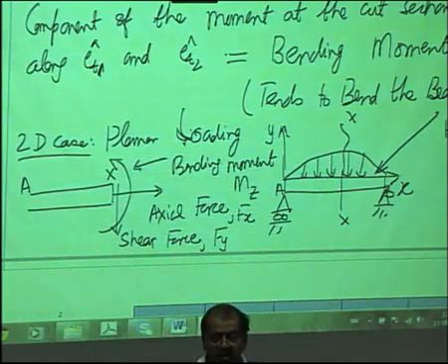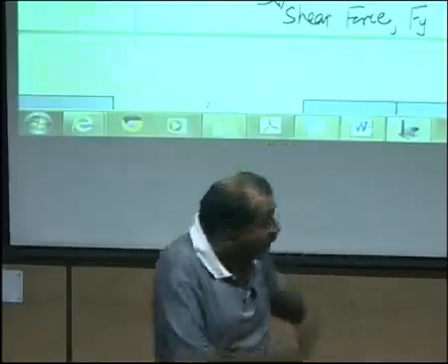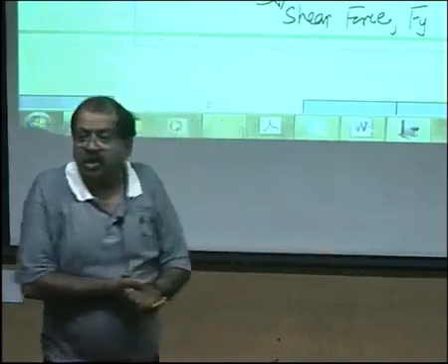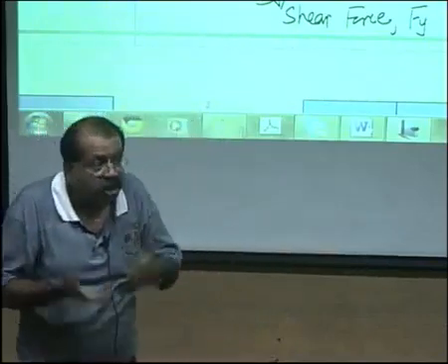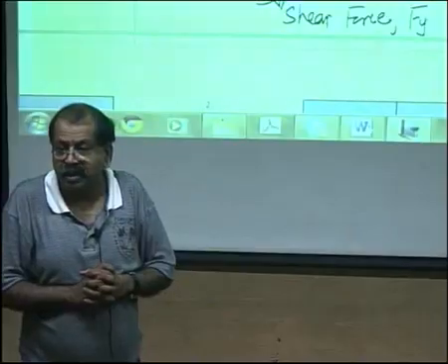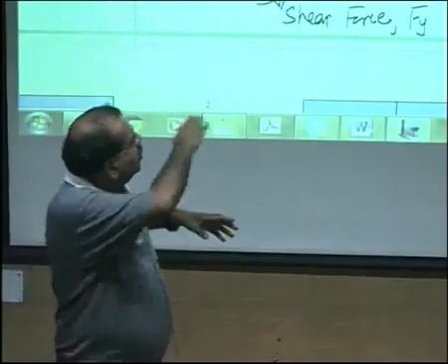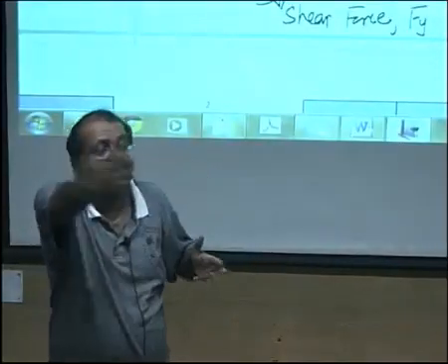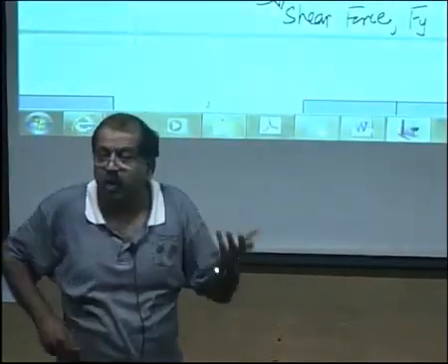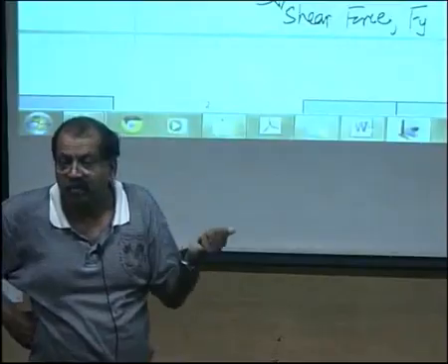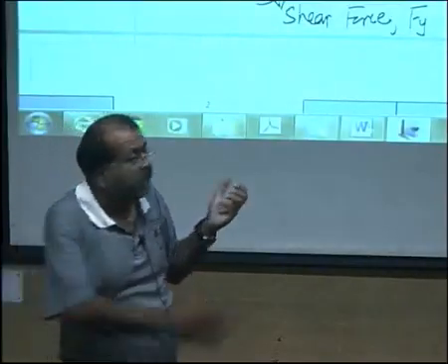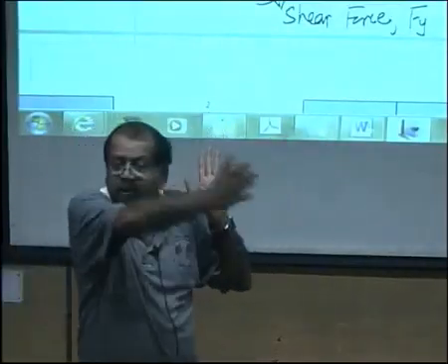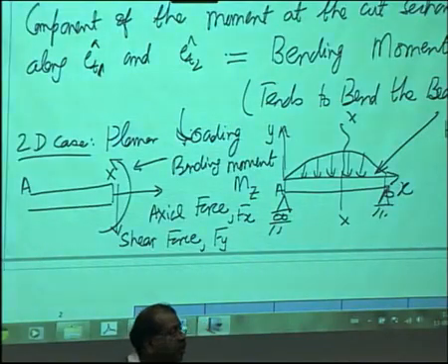what are the bending moments. And leading from this is the concept of what we call a shear force diagram and a bending moment diagram. If I plot the shear force as a function of x along the length of the beam, then this plot is what is called a shear force diagram. And similarly, if I plot the bending moment as a function of x along the length of the beam, then this diagram is called the bending moment diagram.